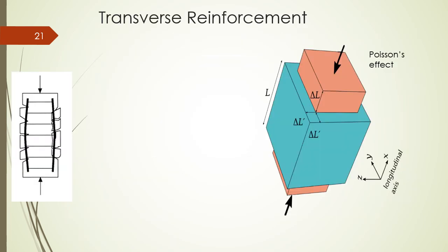So some knowledge you may have is that when we compress something in the longitudinal direction, by the law of conservation of mass, we expect that it will expand laterally. So this is known as the Poisson's effect. And to cater for this, we need to provide links or stirrups. So to do that, it seems I went with 8H20.